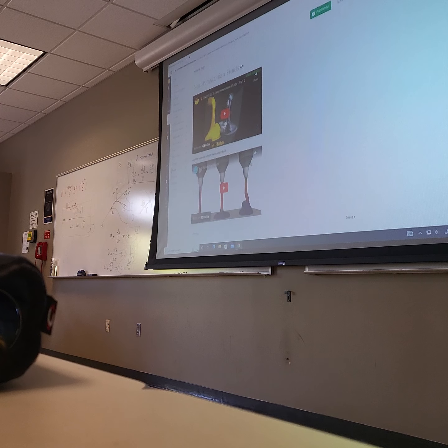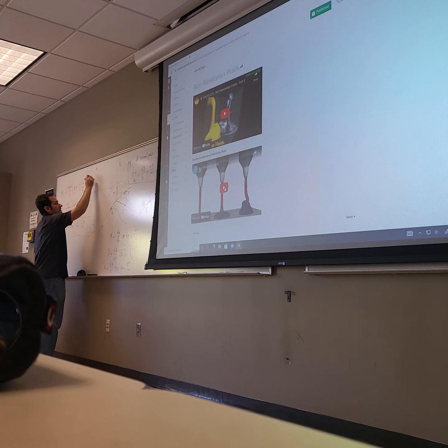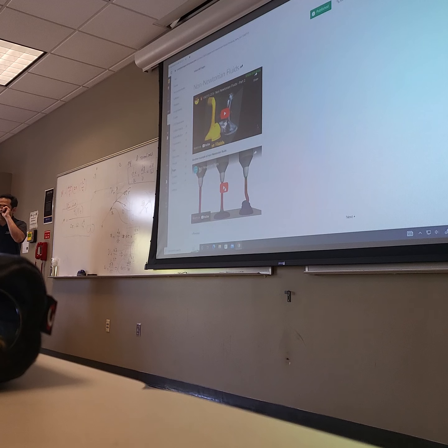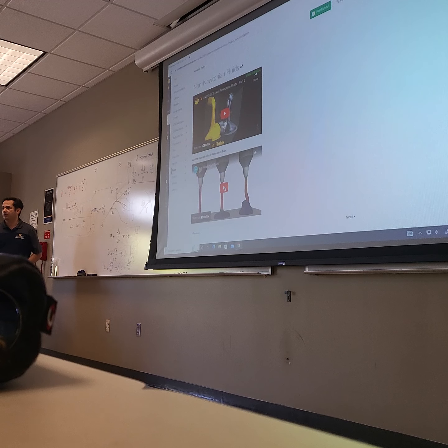Non-Newtonian fluids. Now we got some videos here. I said that between the shear stress and velocity gradient, dV/dy, if the relation is linear, then that's Newtonian. And we said tau is equal to mu dV/dy. So let's say this is shear stress and this is velocity gradient. The slope of the line was constant.